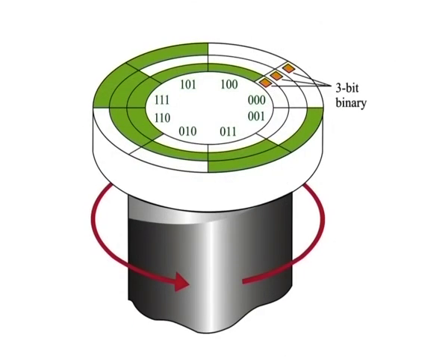As shown in part B, the gray code assures that only one bit will change between adjacent sectors. This means that even though the brushes may not be in precise alignment, there will never be a transitional error.